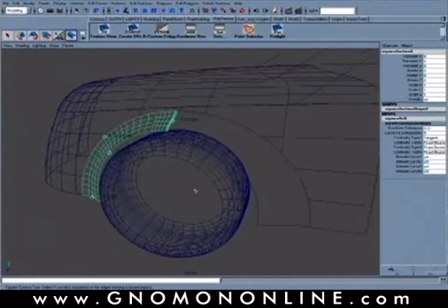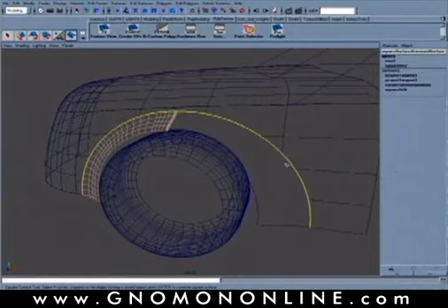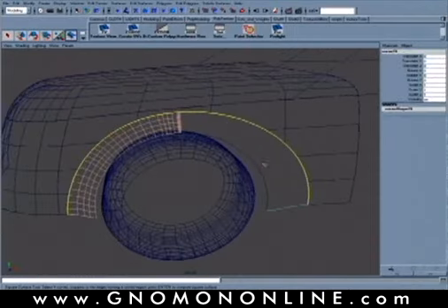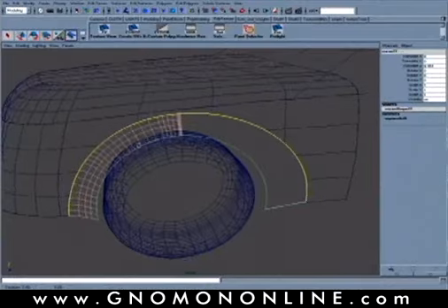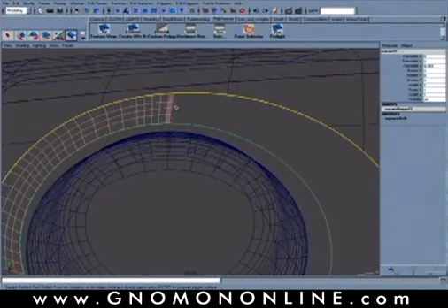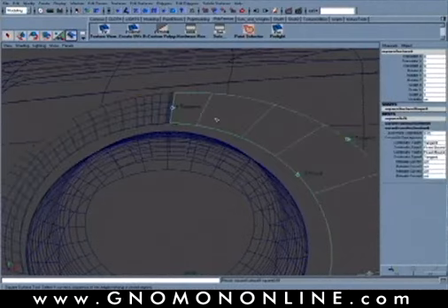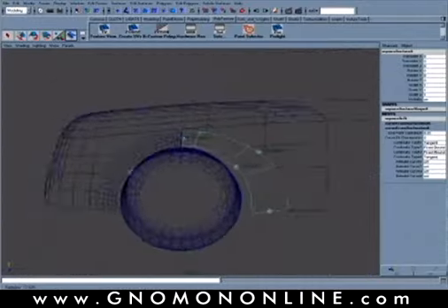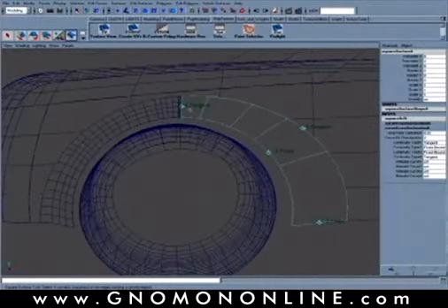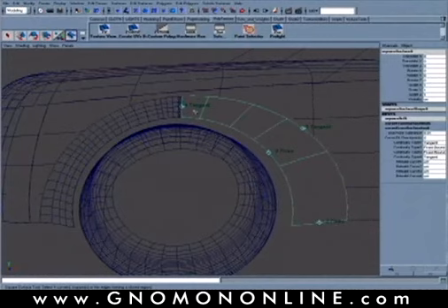So with my Square tool again, I will pick my, say, wheel, the larger wheel cutout that we trimmed, the inside section, then our wheel arch, and then this time we really don't want to use our profile of the original curve. We want to use the edge, which is this isoparm edge of the other curve. So that is going to be used to specify our center line tangent to the other surface, because we already now have another existing surface here.